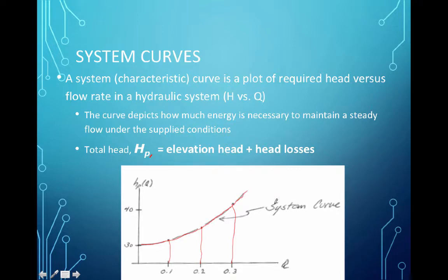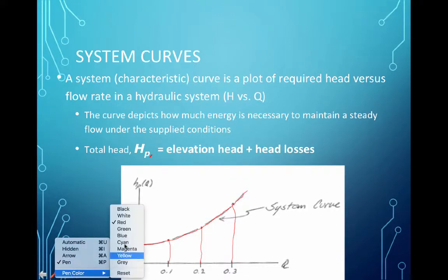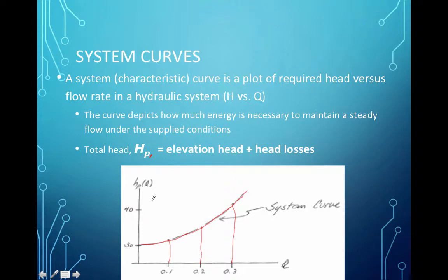Now related to it is the pump curve that the manufacturer supplies, and that tells how much head a pump will generate at different flow rates. They tend to curve downward. And so pump curves look something like that, and where the two intersect is the operating point.